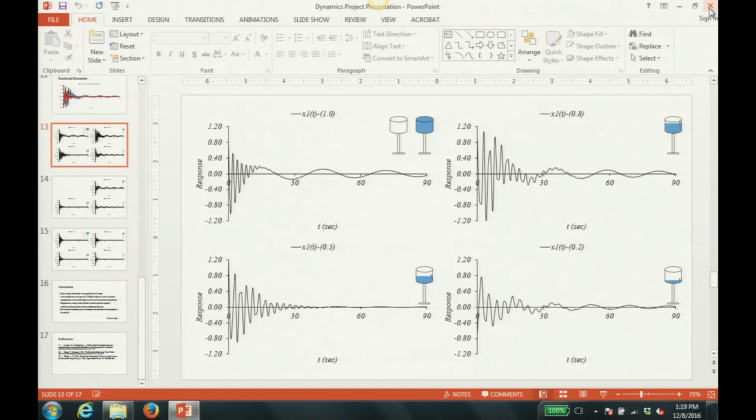They've been developed and researched, and a lot of them have gotten very complicated, but the fundamental idea is just what you've described there: you have a container full of liquid, and if it's moving, it may counteract some of the motions. If you tune it by adjusting the height, the volume of liquid correctly, and it depends on the geometry of the container and all that, you can tune it to reduce the behavior.